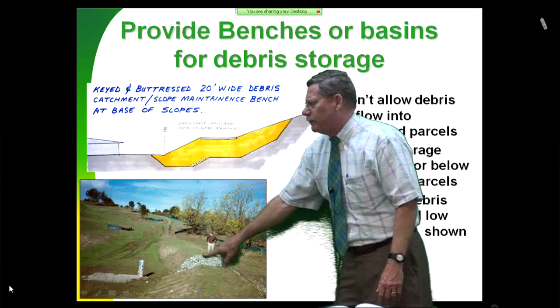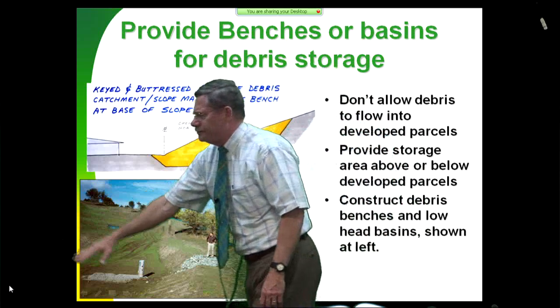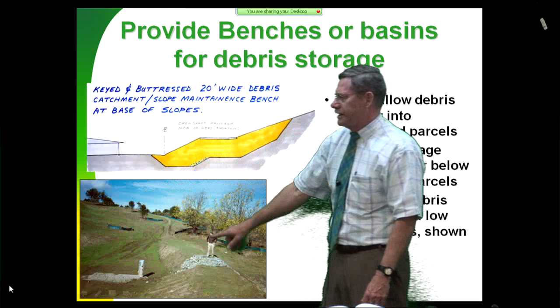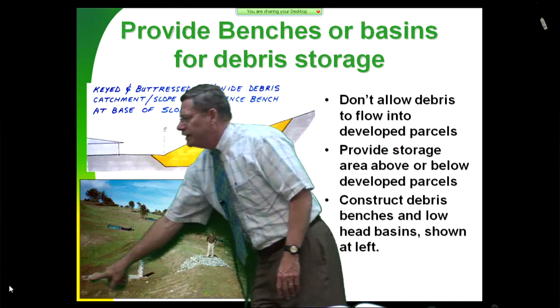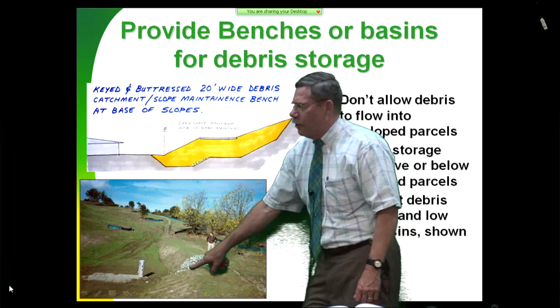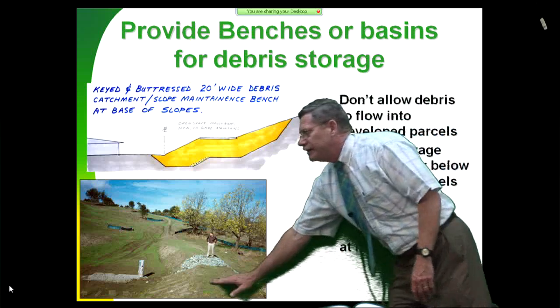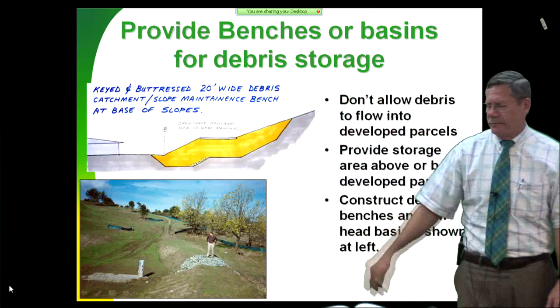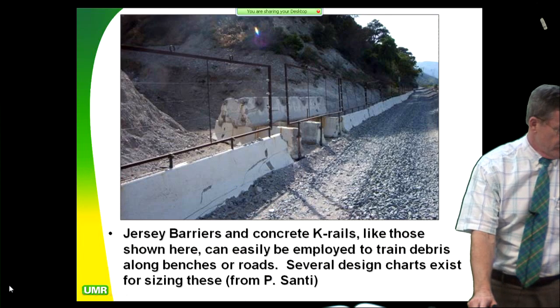This is a temporary basin that we built for a winterization on a grading project. That's me, about 1988, standing on it. I got a little perf riser here, I got a subdrain going out, and I got a rocked overflow spillway. So if you're going to build any kind of dike, you better have a spillway. And we were lucky we never had to test that one, but it did work.